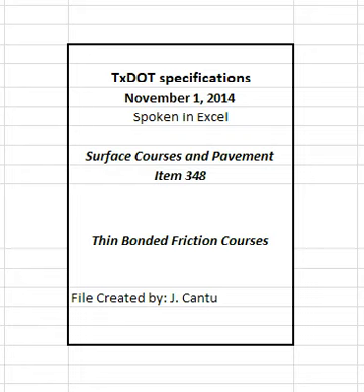Provide aggregate stockpiles that meet the definitions in this section for coarse or fine aggregate. Do not use intermediate or fine aggregate in PFC mixtures. Aggregate from reclaimed asphalt pavement, RAP, is not required to meet Table 1 requirements unless otherwise shown on the plans. Supply aggregates that meet the definitions in Tex 100E for crushed gravel or crushed stone.